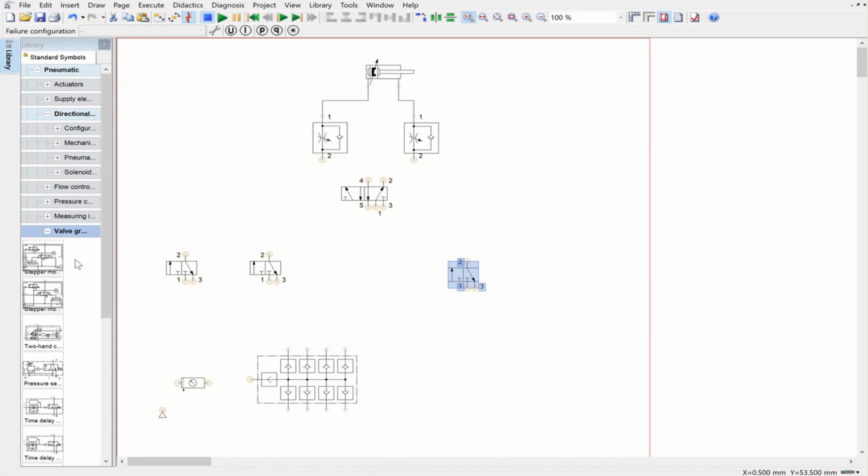And based on the given statement inside the problem, we need to have a normally closed time delay valve, because it is going to stay for a certain amount of time, right, without providing the air to the actuation mechanism for the directional control valve, and from there for the double acting cylinder. Therefore, it's a normally closed time delay valve.